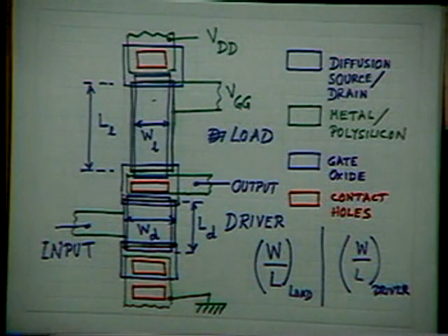Actually, it is not only on, it must be kept always in the linear region. There is no pinch-off of the channel. Normally, on the drain side, there is a pinch-off of the channel when the transistor is in saturation. Please don't confuse this saturation with the bipolar transistor saturation. Conceptually, they are totally different. By saturation here we mean the region where the drain current is independent of VDS.